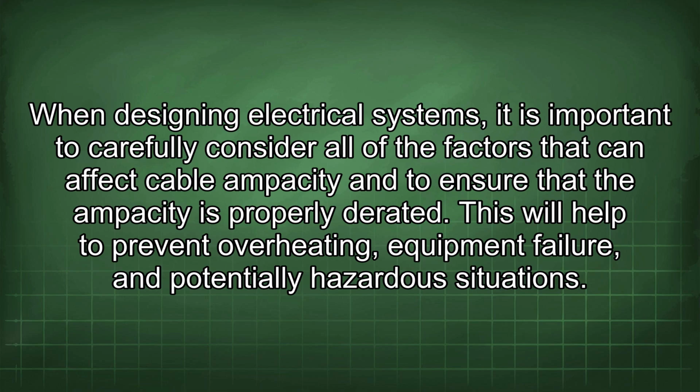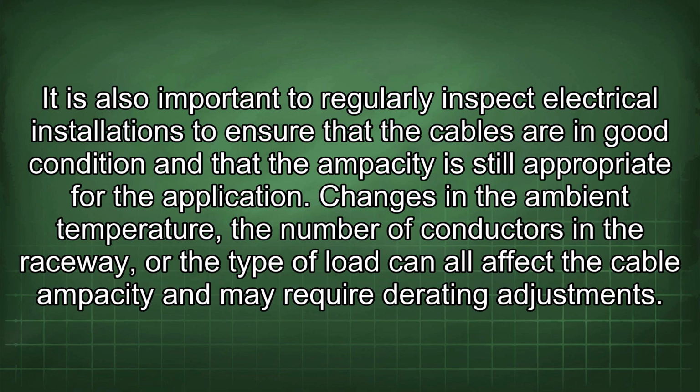When designing electrical systems, it is important to carefully consider all of the factors that can affect cable ampacity and to ensure that the ampacity is properly derated. This will help to prevent overheating, equipment failure, and potentially hazardous situations. It is also important to regularly inspect electrical installations to ensure that the cables are in good condition and that the ampacity is still appropriate for the application.